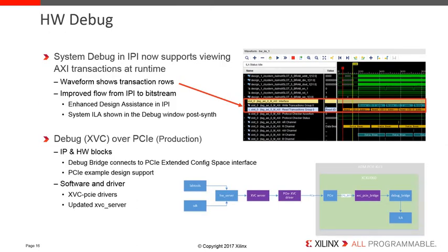Now switching gears to hardware debug, as there are many features that have been added to increase productivity. System Debug in IPI now supports viewing of AXI transactions at runtime in the waveform viewer as shown here. There is also improved flow from IPI to bitstream, including enhanced design assistance in the IPI, and the ability to show the system ILA debug window post-synthesis.